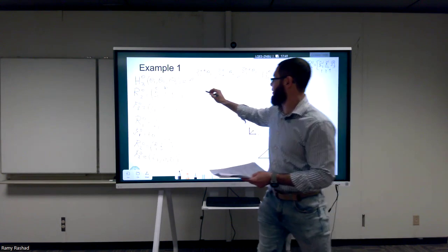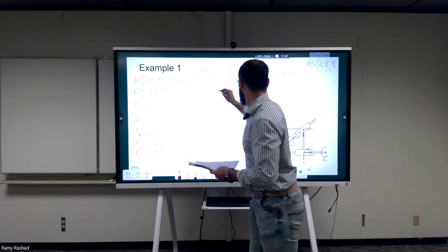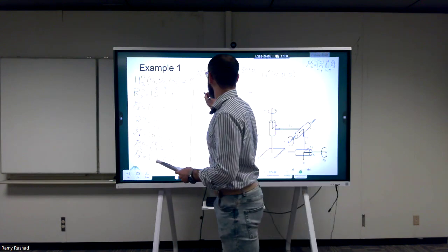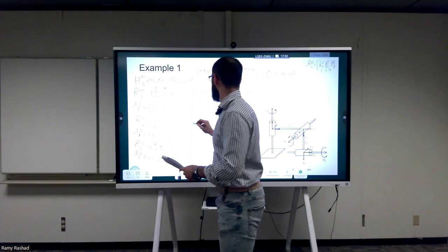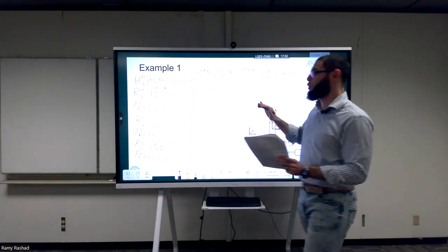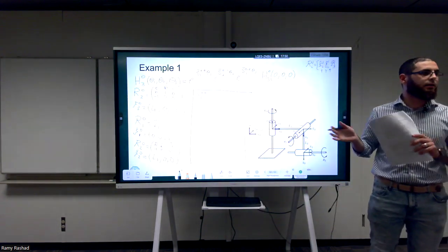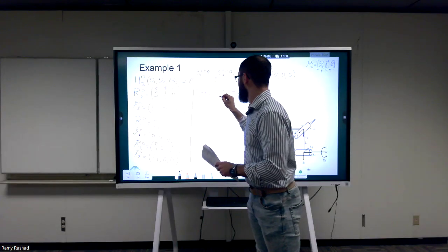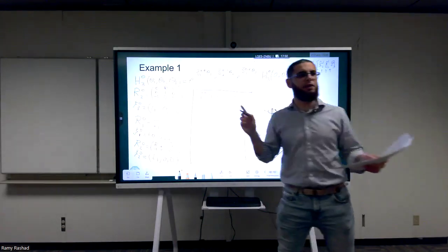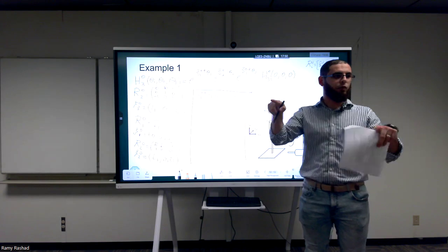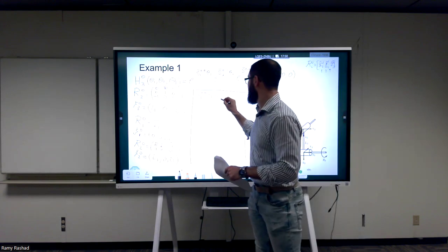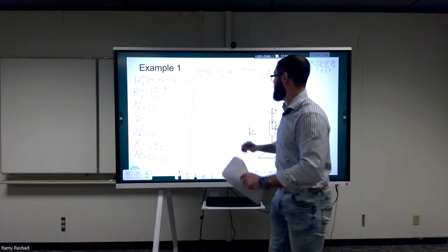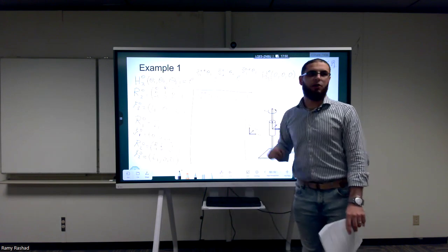What about here the screw axis? So S1, 0, 0. I have 3. First of all, is it revolute or prismatic? It's revolute. This means it will have some omega and some v. Remember, the omega and the v are just what the book called. So this is omega 1. We're just going to be calling omega 1 and v1. These are 3 numbers and these are 3 numbers.